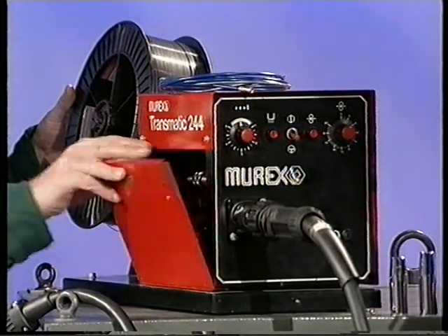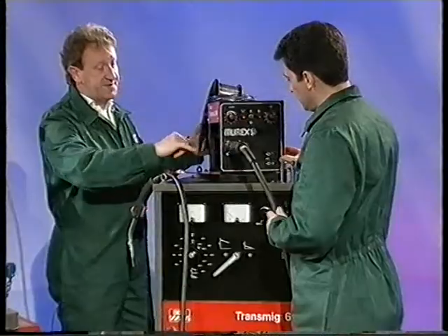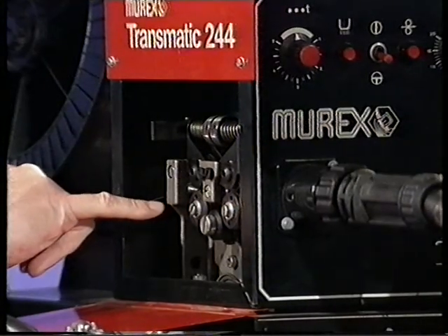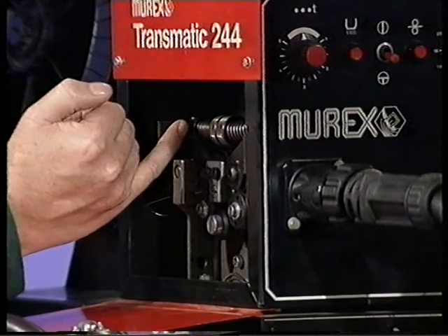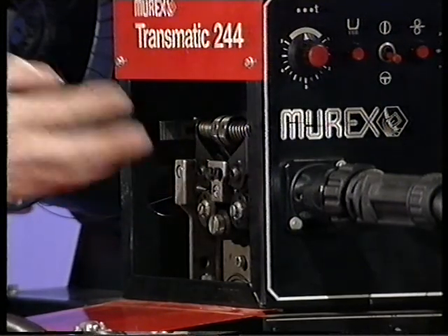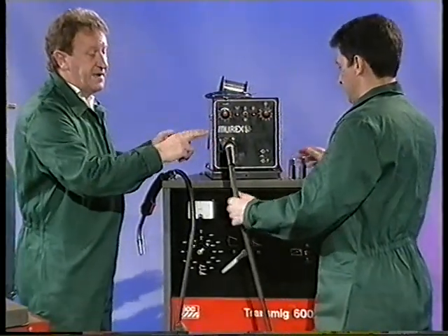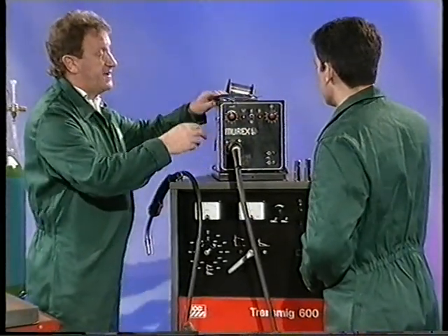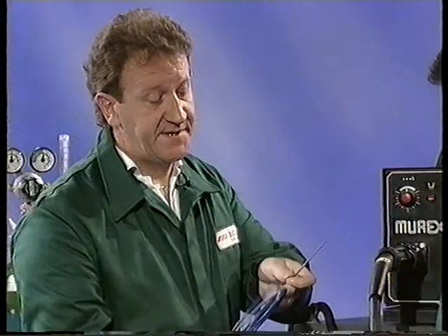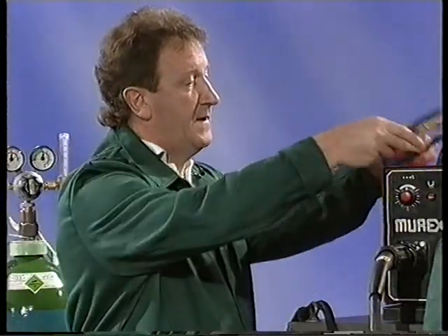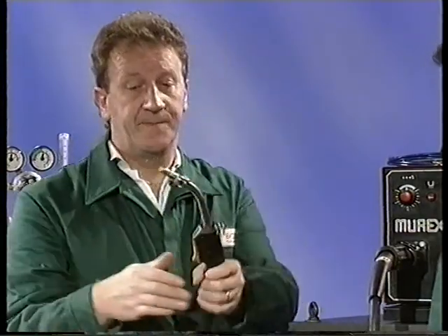That's fed through the wire feed unit, and you can see that we have wire feed rolls in here that have different grooves for the different diameters of wire. There's a tensioning device here that can be adjusted for the different diameters of wire. The wire is then fed through into the torch, and there is a liner inside this torch, and for carbon manganese steel, it's that type of liner that is recommended. Yeah, quite robust.